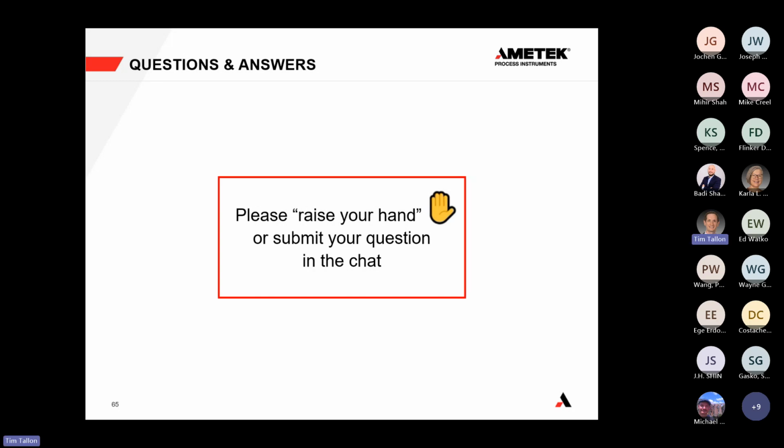Okay, great question. So I see another question in the chat, and feel free to keep asking. This presentation's for you. So the next question is, do you have a general reference for where you would recommend to install the analyzer? Yes, I sort of gave some answer to that earlier. The American Petroleum Institute, the 556 recommended practice, second edition, recommends that for fired heaters, the flue gas analyzer be located right outside the radiant section. You need enough time for the combustion to take place. You need to be outside the burner flame and the burner envelope.